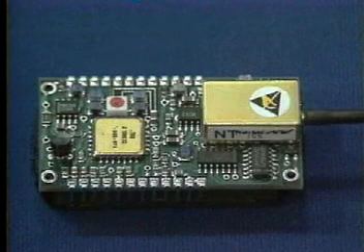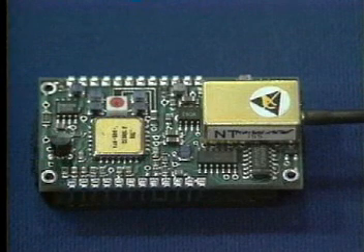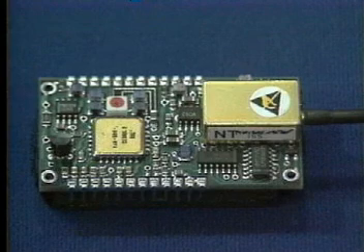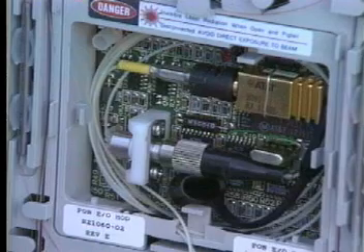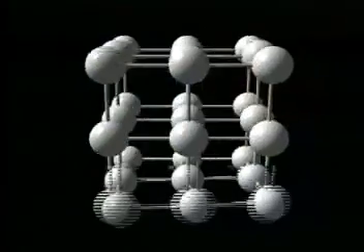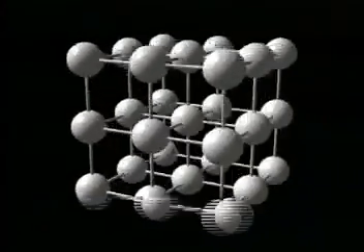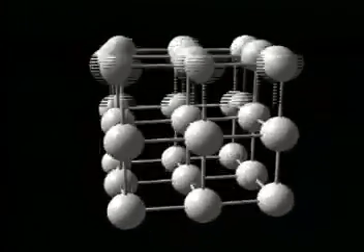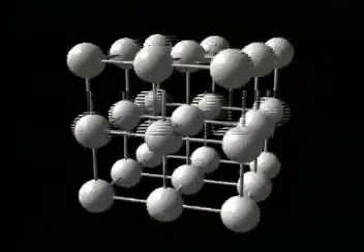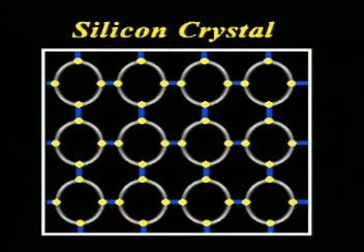All semiconductor devices use a basic structure called a p-n junction in their operation. This includes diodes and transistors, as well as LEDs, lasers, and photodetectors used with optical fiber. Silicon atoms with their 4 valence electrons bond together to form the crystalline structure of solid silicon. Silicon atoms form covalent bonds with their neighbors by sharing their valence electrons. Each atom has access to a full valence shell of 8 electrons, 4 of its own and 4 from surrounding atoms. This is a very stable condition with no free electrons available.